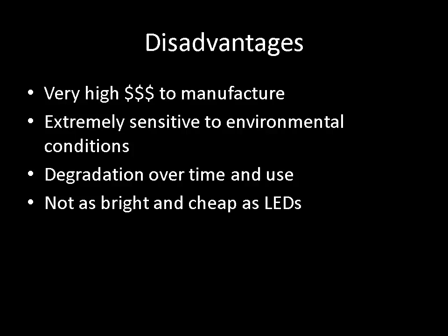With its many benefits, it makes you think why regular LEDs are not yet obsolete. This is mainly because of the very high costs in fabricating OLEDs. All parts of the OLEDs are extremely sensitive to environmental conditions during and after fabrication. Therefore, it is not uncommon for OLEDs to degrade in luminance over time and use. The degradation of OLEDs can also occur at different rates for different colors and can cause colors to look skewed over time.